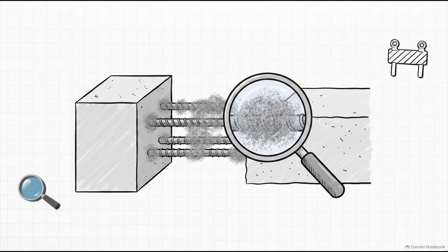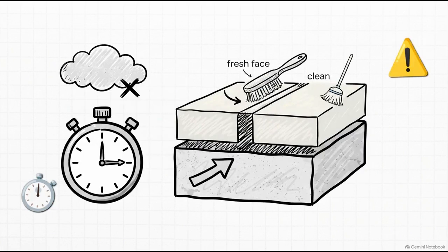Overspray loves to collect on the exposed rebar near these stopping points because, well, the crew was just shooting right next to it. That steel absolutely must be properly cleaned before placement resumes, because if it's coated in hardened overspray, the new shotcrete cannot fully encapsulate the rebar, and you've got a structural problem. And of course, the reality of the field is that things go sideways.